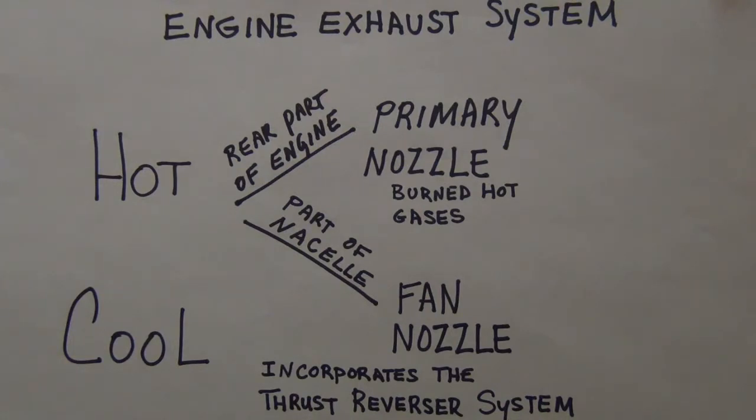All right, and on the management part, remember I mentioned the landing gear, your LGCIU, which is the landing gear control and interface unit. The HCU, your FADEC, has to get the information that the plane truly is on the ground, because that's the only time that thrust reverse can be deployed, and it has to get that information from there.